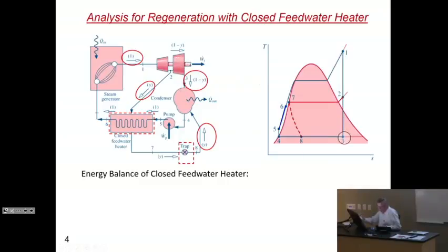in the condenser where it is condensed. Well, where is it condensed? Well, it condenses to point 4 ultimately. But what happens in the feed water heater is that the enthalpy that comes from point number 2 is used to condense the steam that was in this line, in contact with the cold water that comes from the pump.